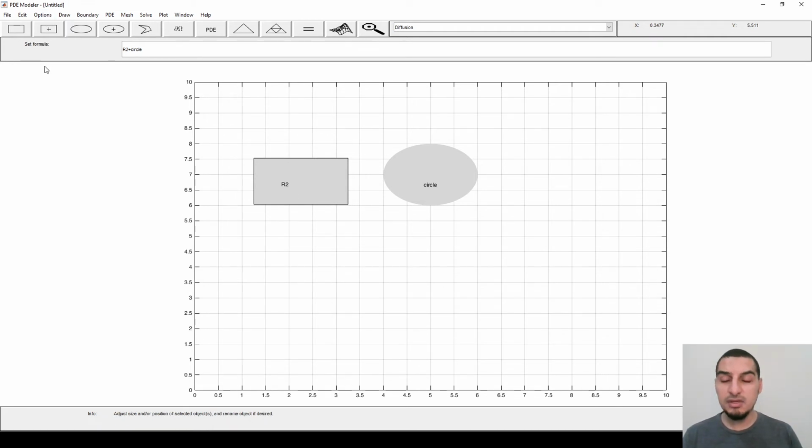One other option that we didn't mention before is the option of snap. By snapping, I'm telling the software that any corner or any point I'm gonna start with must be on an intersection on the grid line. So let's say I'm drawing a shape here. It's gonna start with a point on the grid line, and it's gonna end with points on grid lines.